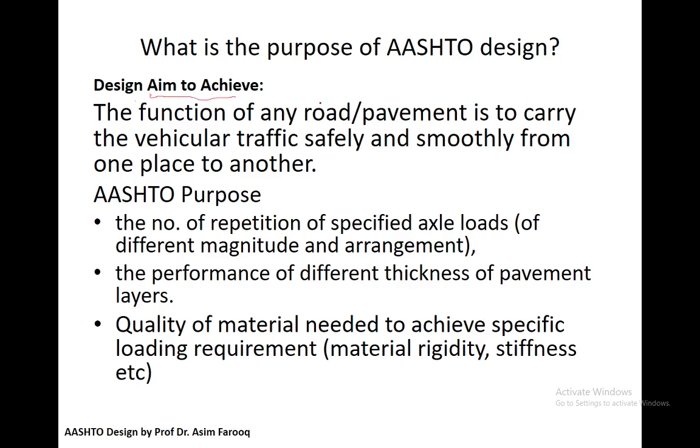Before going into detail, the aim of the design is to design a pavement which can carry a load, and divide and distribute the load from the top to the subgrade layer, and it should also provide reliability to the vehicles as well as to the people. So the first purpose of AASHTO is that we can model and design for the dynamic repetitive load, when we have different magnitudes and different arrangements such as tandem axle, tri-axle, and so on.